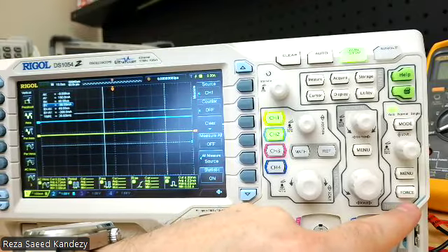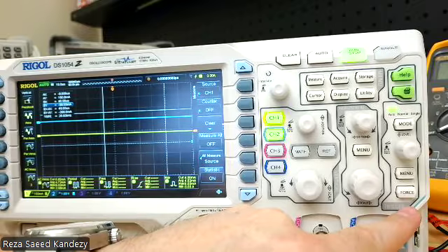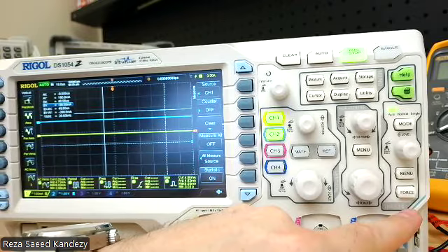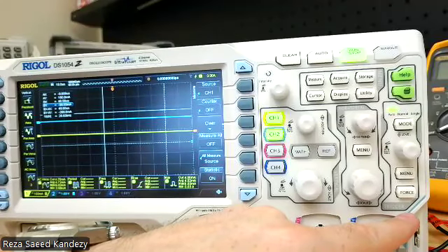This force option forces an immediate capture. Regardless of what triggering condition you set, you can force an immediate capture of your signal. It is useful when testing your setup or when you want to see the signal without waiting.